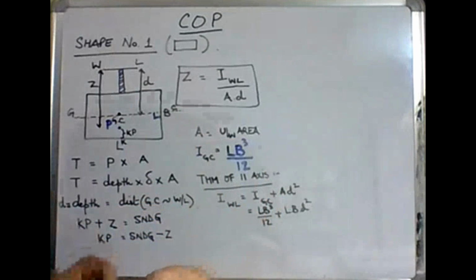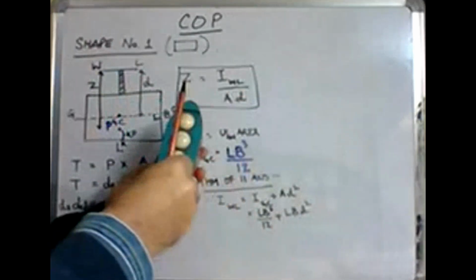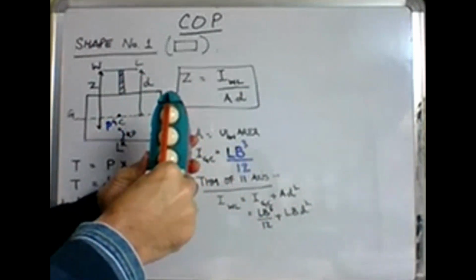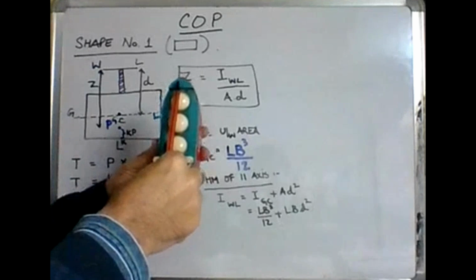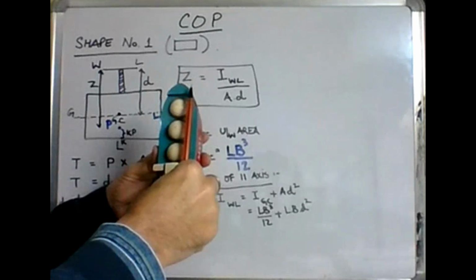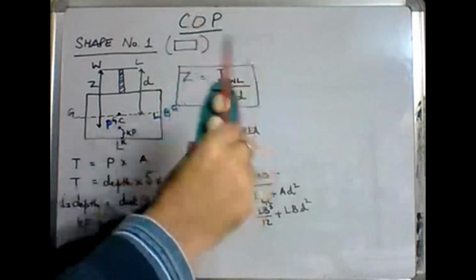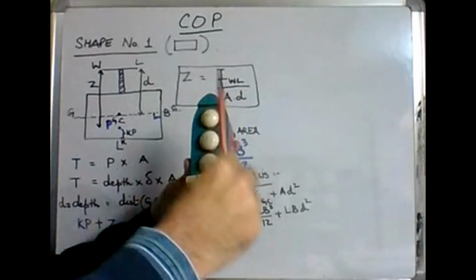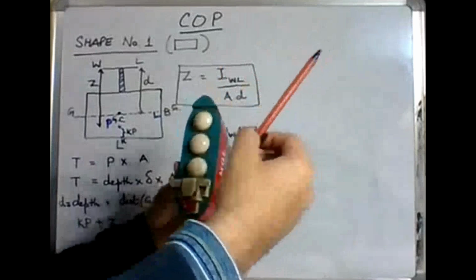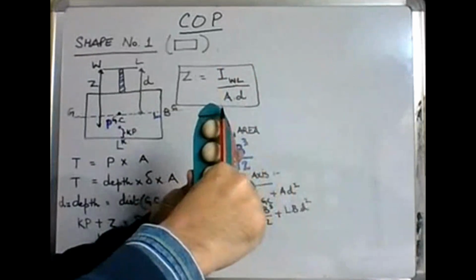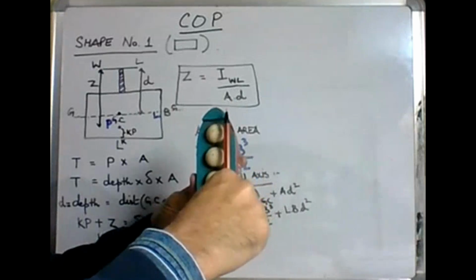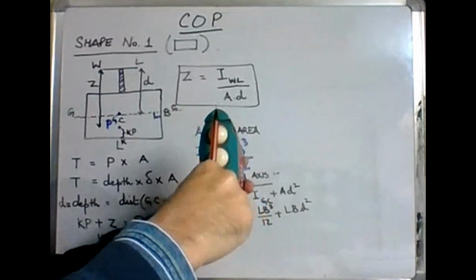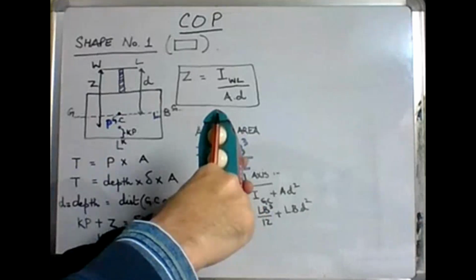ये बेसिकली अगर मैं इसकी एप्लीकेशन जहाज के ऊपर बताऊं तो ये है जहाज की सेंटर लाइन. ये है मेरा साइड टैंक. मेरा साइड टैंक जो है उसका मोमेंट ऑफ इनर्शिया, सपोजिंग DB नंबर 2 या DB नंबर 3, would be LB³/12 about the center line of that tank. मुझे चाहिए moment of inertia about the center line of the ship.